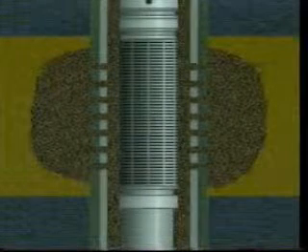The damage caused by perforating is cleaned out as completely as possible by backflushing, washing, or underbalanced perforating. The key to an effective cased hole gravel pack is to, first, create a cavity beyond the cement and damaged formation, and then pack this cavity from the undamaged reservoir through the perforated casing and into the casing screen annular area with a high permeability gravel.